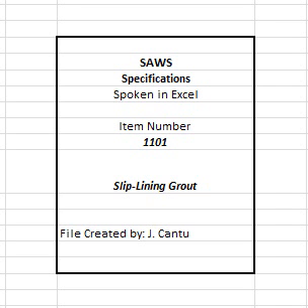B. Detailed descriptions and drawings indicating proposed locations of surface mixing equipment, subsurface injection points, flow lines, waste grout recovery, grout pressure limiting equipment, bulkheads, and venting system. Show details of bulkhead design. C. Qualifications and experience of grout mix applicator. D. Grout mix design and trial mix tests, with set time, compressive strength, viscosity, and density test results.